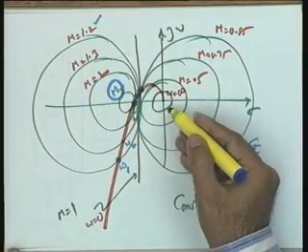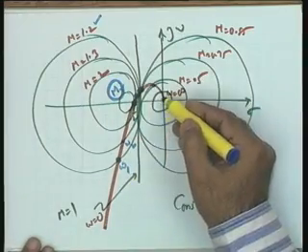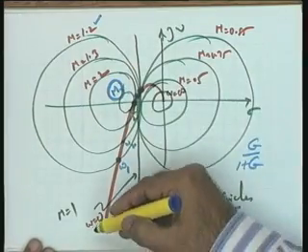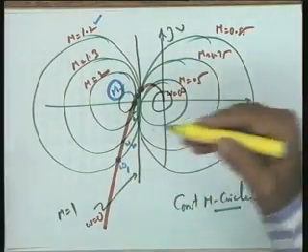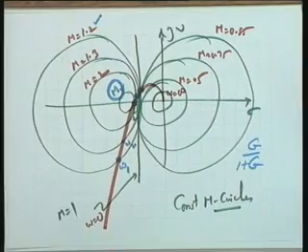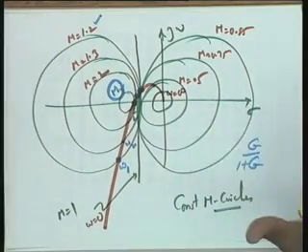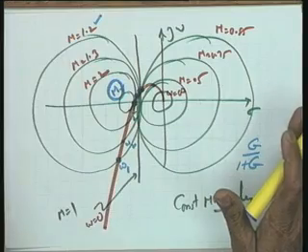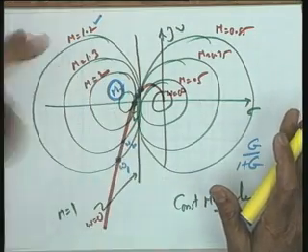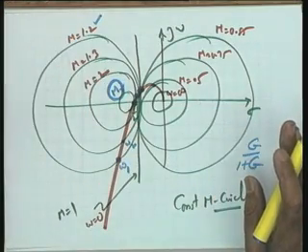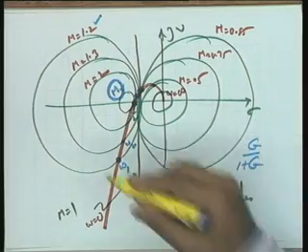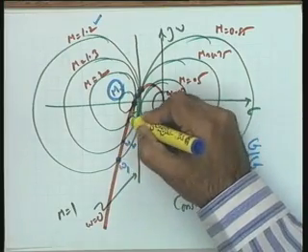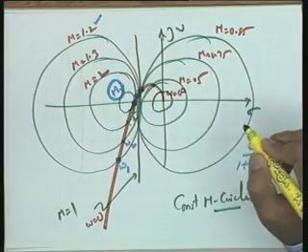So, you take any frequency response, the Nyquist plot, and see the points of intersection. At the points of intersection you can get the magnitude of the closed loop frequency response. That way, for a unity feedback system it becomes easy to get the response without calculations. Yes, question please. But we will have to find the frequencies of intersection exactly. You are right. The frequencies at the points of intersection you definitely will have to find exactly.